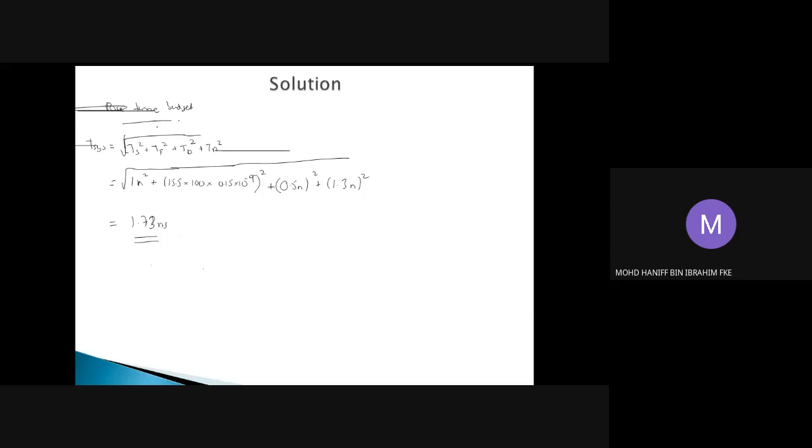Okay, so now I'm going to use the power budget. The second method is based on the power budget method. If you base on what we have learned in the previous lectures, last week's lectures, if we can recall, the power transmit, the PTX, will be equal to the power receive, plus the channel loss, and if possible, we are going to have the system margin.